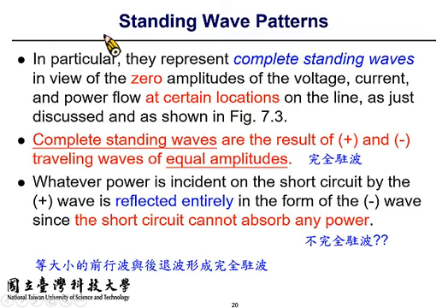And there are other conditions that can produce a complete standing wave, including short termination and open termination. And if you terminate the transmission line with an inductor or a capacitor, because inductor, capacitor, short circuit, open circuit do not dissipate energy on those terminations, they all form a complete standing wave.